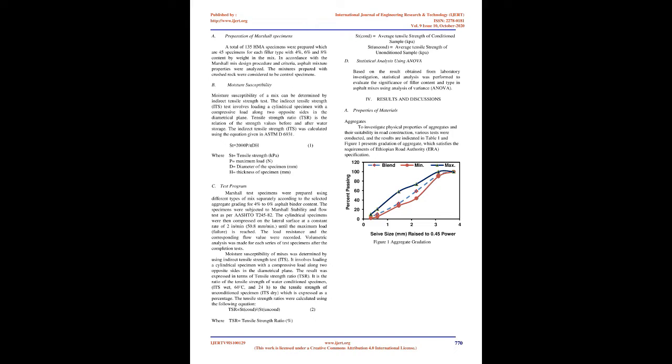The construction industry utilizes natural sand mainly from stream beds, which are commonly derived from quartzo-feldspathic basement rocks, sandy marine sediments, and alluvial deposits. 20. Economic evaluation of asphalt mixes prepared with 7% and 7.85% wood ash and fly ash filler yields less cost as compared to control mixes prepared with crushed rock fines. However, mixes made with fly ash filler indicated lower cost than mixes containing wood ash filler.